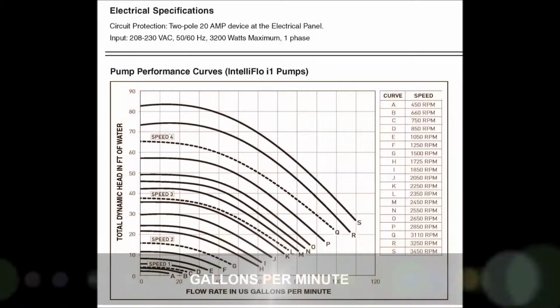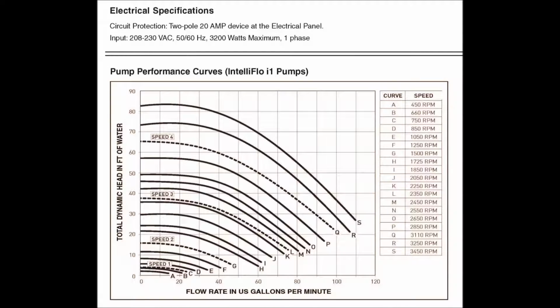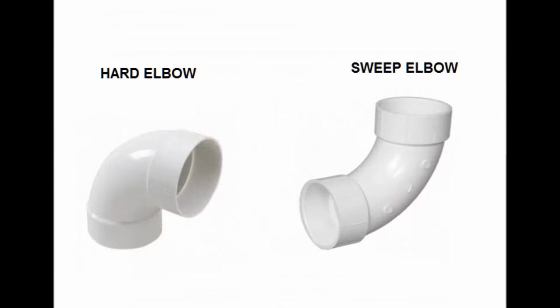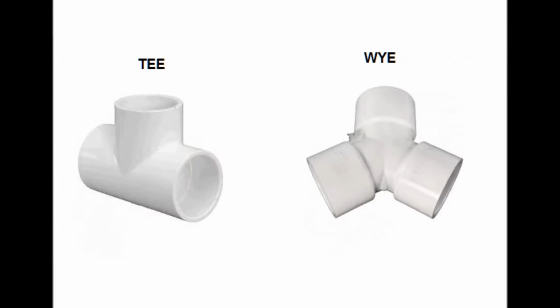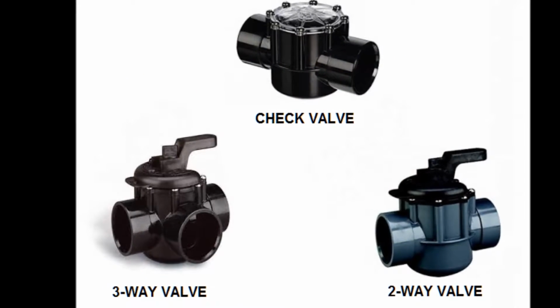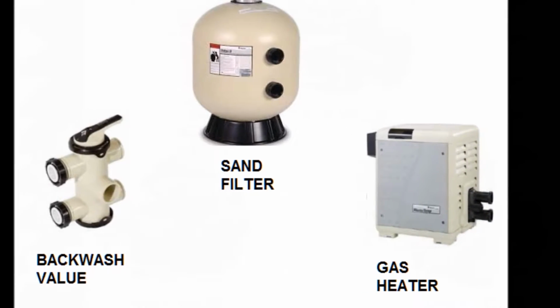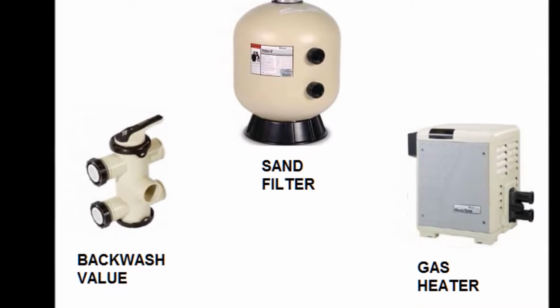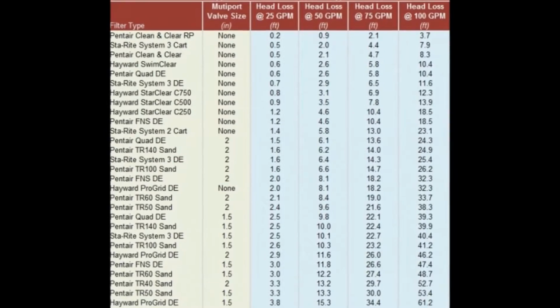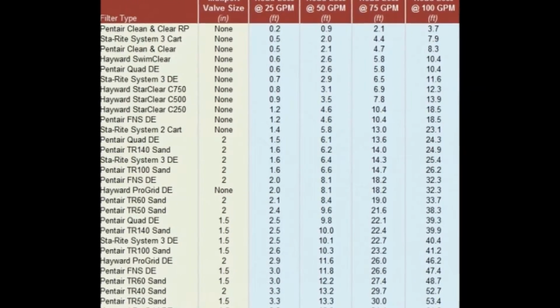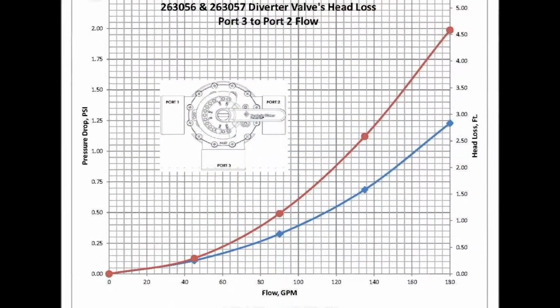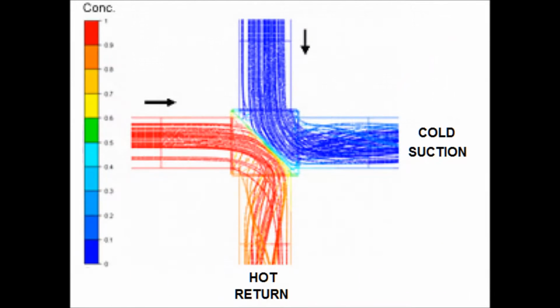If the piping system with all its interrelated components such as elbows, T's, valves, etc. pose too much restriction, well then, the pump's impeller will provide more pressure than flow. This restriction is referred to as hydraulic head loss, or HHL.